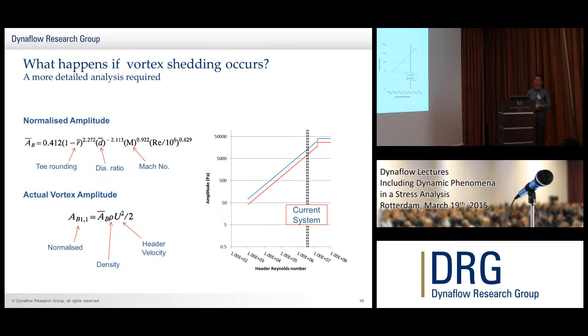Now you're going to ask why there is a step at this point. This is because over a Reynolds number of 16 times 10 to the 6, the method from Rogers just proposes a standard, straightforward limit of 10 for this value, which is not dependent on any of these parameters. But most typical systems will be below 16 times 10 to the 6.